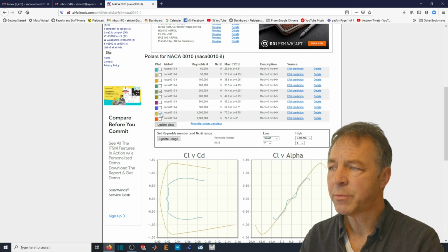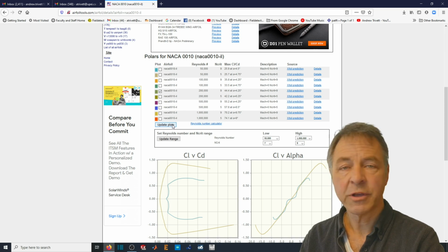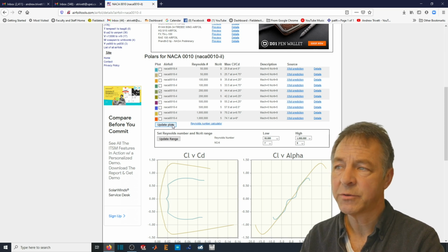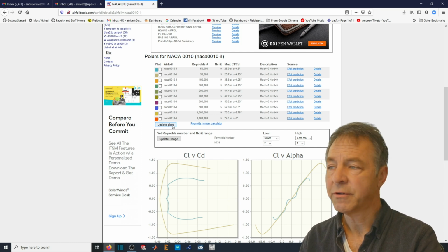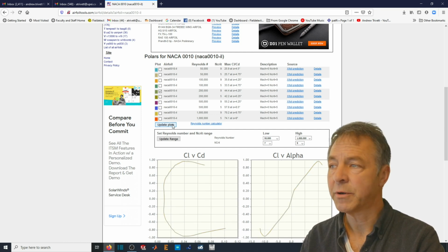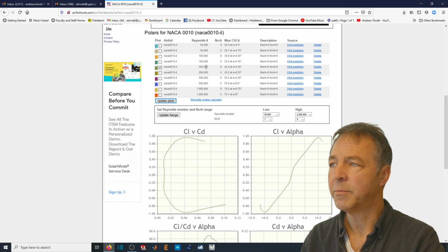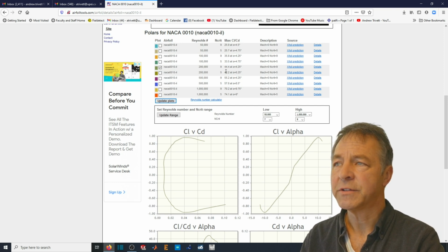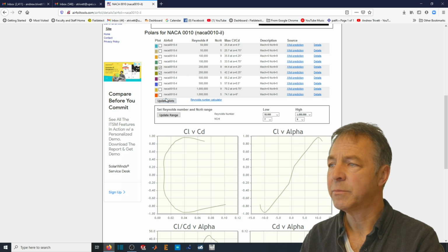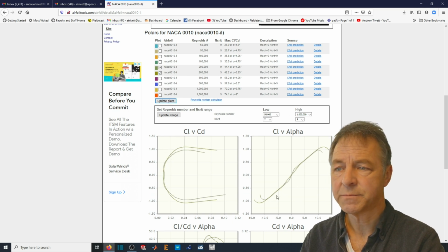And so for the example that I'll be using in this series of videos, I'm going to be looking at something where the speed is around 200,000 to 250,000 Reynolds number. And so if I just look at that Reynolds number by clicking the choices here, that shows me the Reynolds number range, and it shows me the angle of attack, maximum lift at an angle of attack, and that's helpful in showing the results.